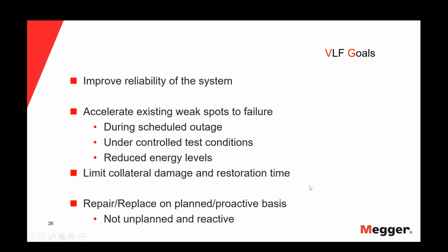So the goals of the VLF test are to improve the reliability of the system and accelerate the existing weak spots to failure, of course, during a scheduled outage, under controlled test conditions, and at reduced energy levels. This last is very important. Having a fault when the cable is in service is not the same as having a fault during a VLF test. The big difference is the amount of energy that will be liberated through the fault.